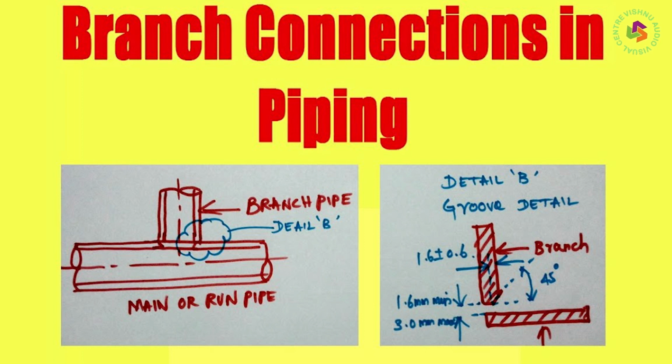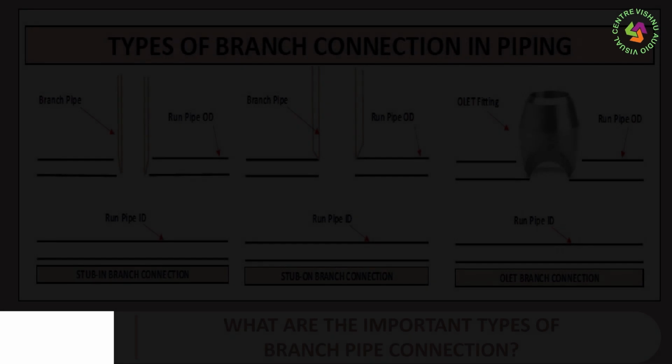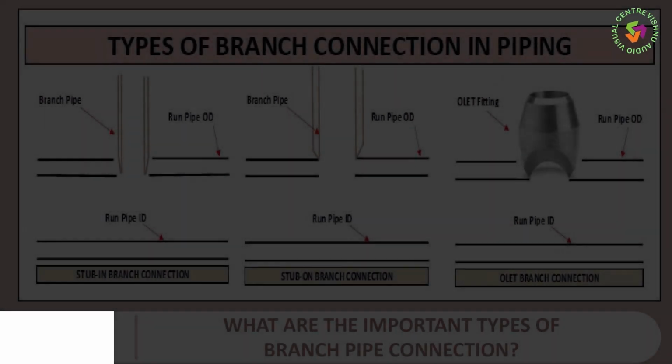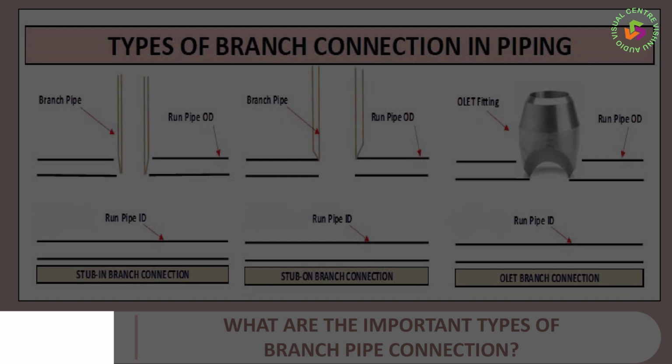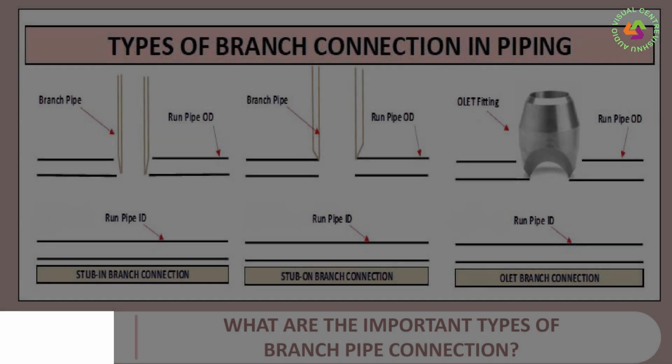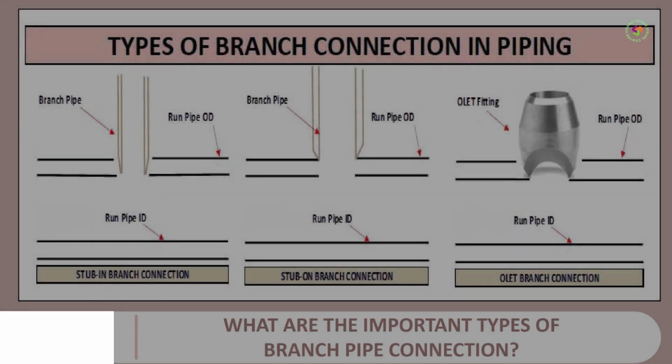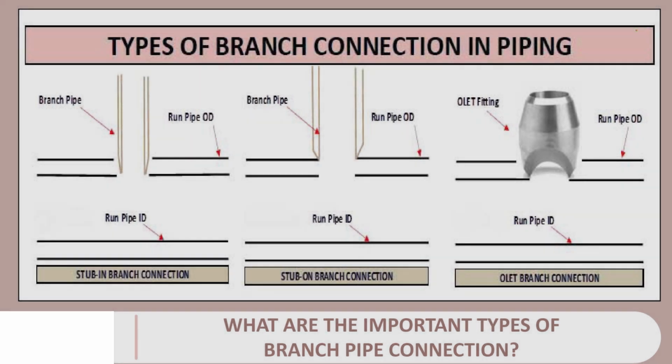The head loss in the clockwise direction is taken as positive, whereas the head loss in the anti-clockwise direction is negative. If the net head loss in each loop is equal to 0, then the assumed values of Q in each pipe in that loop are correct. If not, a correction has to be applied for each pipe in that loop.